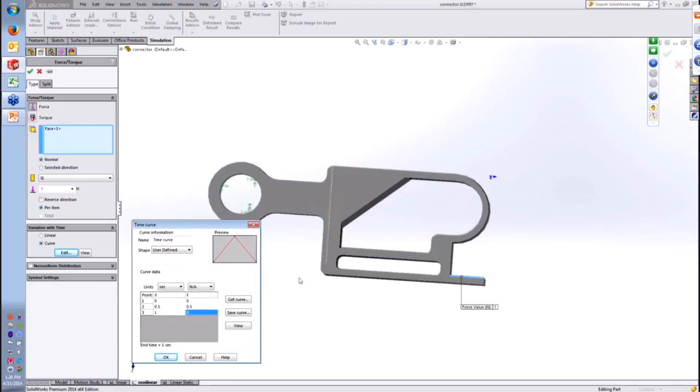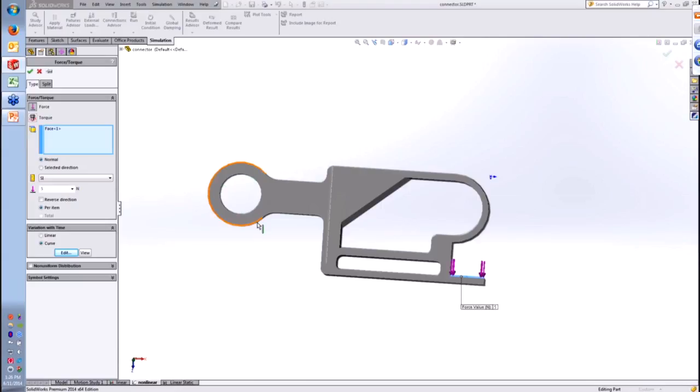You can see here that in this particular case, what we're doing is punching in a few data points to simulate that this same 5 Newton load is being applied slowly from 0 up to that full value. And then it's going to be removed at the same rate, so that after about 1 second here, we will have put the load on all the way and then taken it off, which is going to allow us to see if the part has yielded, what is its final shape, even after we've taken the load off, because it will have some permanent deformation in there.